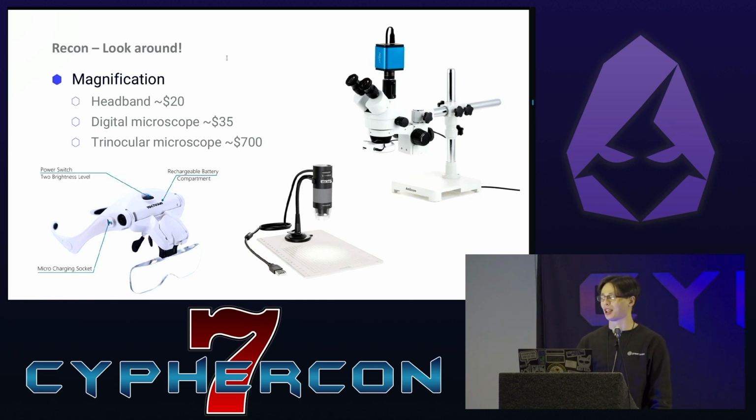If you're doing this a lot and you really want to make the investment, getting a stereo microscope is really fantastic. You keep your depth perception. It makes soldering small components really easy. And if you get one with a trinocular port, like the one shown on the right here, you can put a camera in that top tube. So again, for documentation or reporting purposes, you can get some nice professional zoomed in images so people can really see what's going on.